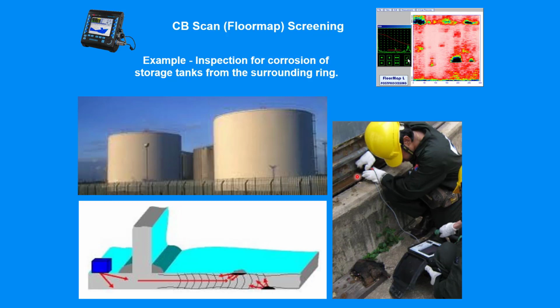You see here, this guy puts a probe on this side, on this area, and it's beaming inside. And this plate is tested for corrosion, and this is the plate down here in this illustration. So the probe is here. There's some sound traveling inside. Then a guided wave runs through. It's reflected from some corrosion, and it gives an indication about the distance of the reflector. So this is the concept, and then you get a quasi C-scan image like this one.